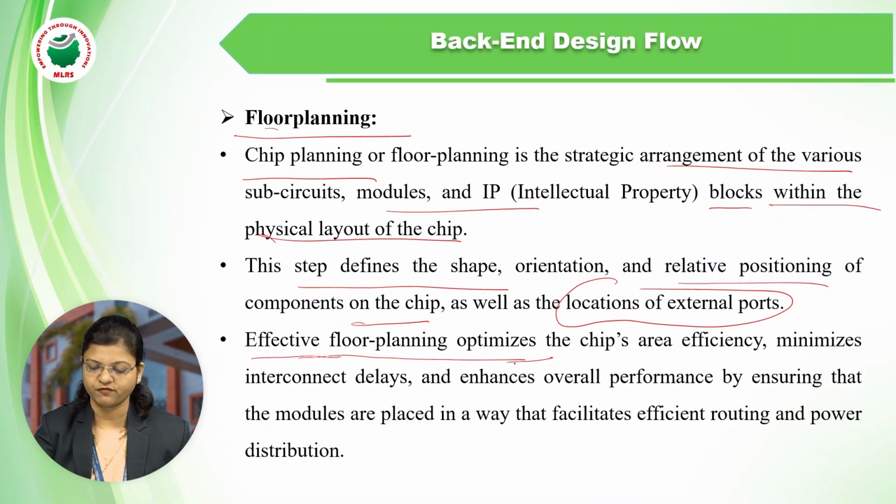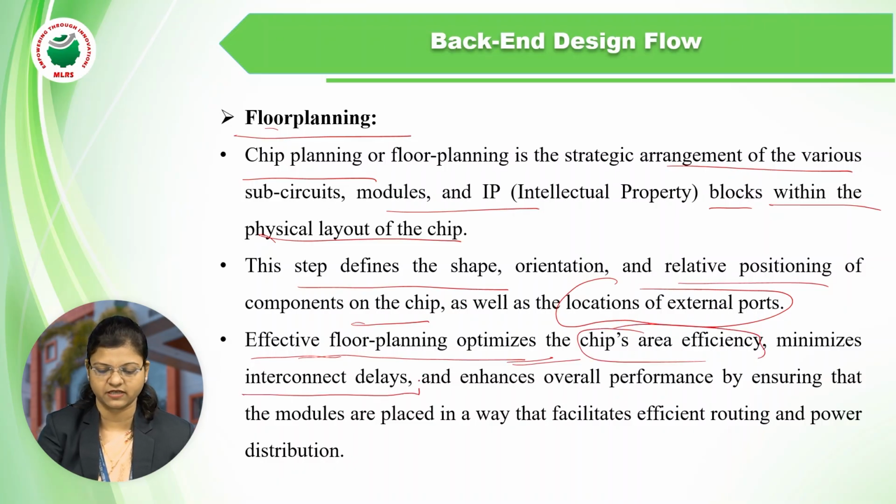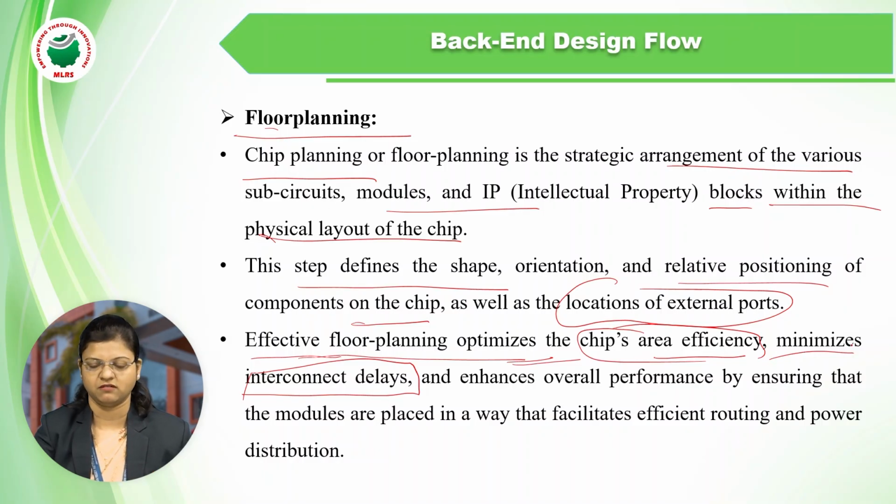So what does floor planning do? Floor planning optimizes the chip area efficiency, and it minimizes the interconnection delays as well. If we do proper floor planning and arrange all the circuits and modules in a proper way, then we can have better area efficiency, meaning within very little area we can arrange all the components.